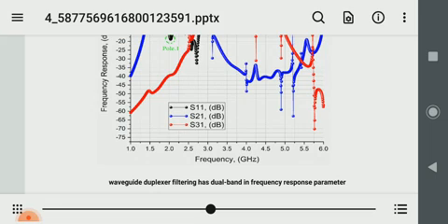The simulation results show a reduced return loss, the S11 parameter in the scattering parameter category, improving the signal filter in wideband frequency, and improving S21 and S31 for dual bands in the frequency response.